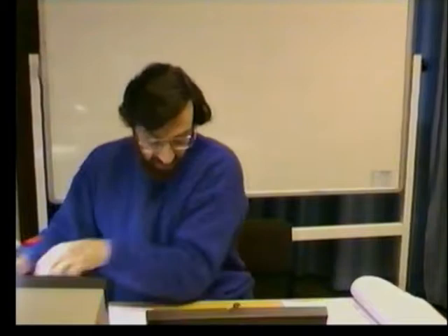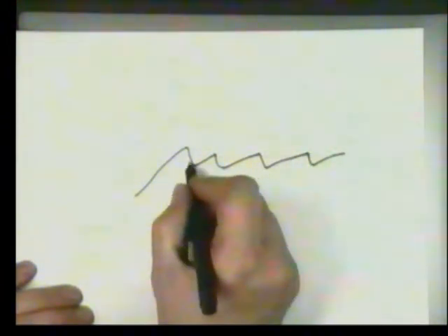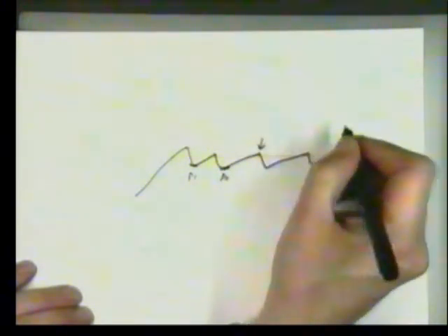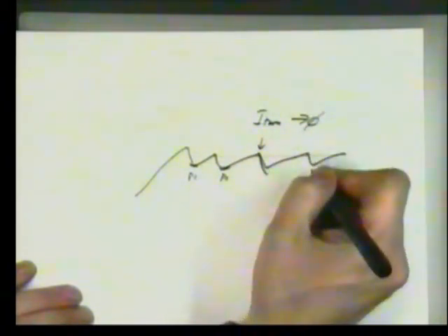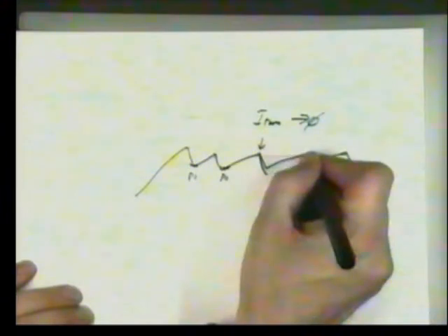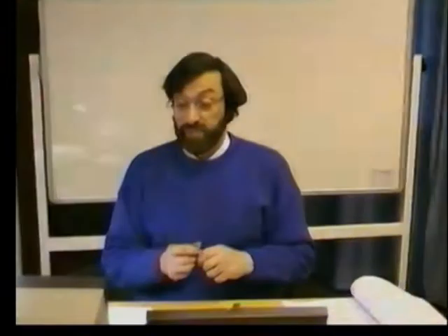And the response characteristic you'll get with that looks something a bit like this. Here you get a reasonably smooth response because that's PI at that point. Here it's a very sharp discontinuity because suddenly the control signal has been switched off and it just suddenly drops back down. Now, if your actuators can accept high-speed changes such as that, then integral reset will work for you. But there is an even neater software solution that you could use.